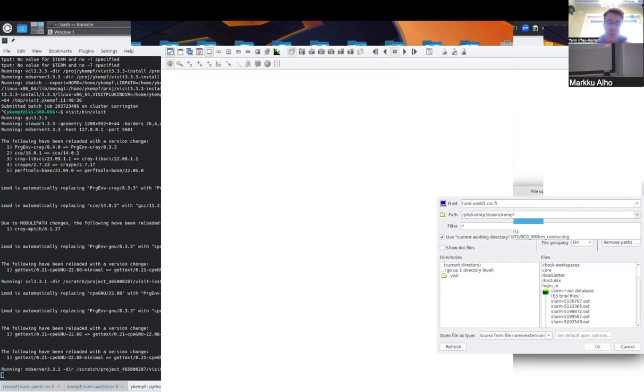So it is a bit redundant, but on the other hand, what you could also do, and that we do in some tests, is have a certain set of conditions in the box as defined in the config file, but a different set of input conditions from the wall. Say you want to push a pulse into your simulation, you could set that in the upstream file and have that propagate into the box. Some of these tests are admittedly more of a technical nature, but if you want a traveling shock or traveling perturbation moving into your box, you could parameterize it in that upstream file as well.